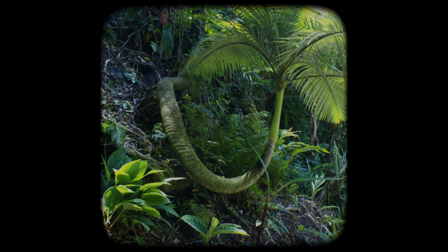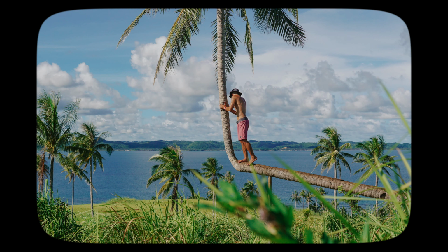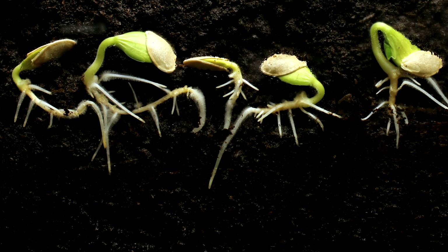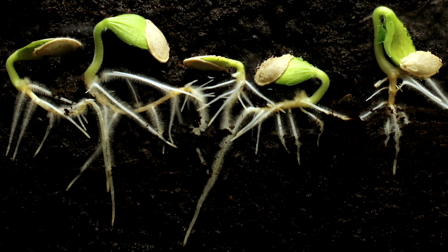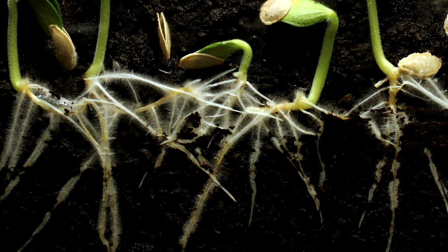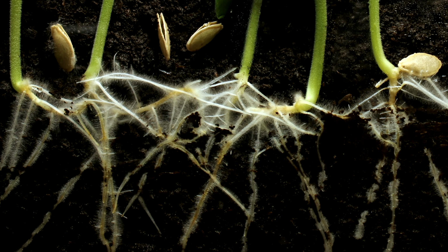When a tree grows on an inclined plane, it tends to straighten itself up through tropisms, that is, by growing towards the sun, and this reduces the total overturning moment that the roots have to resist. It is observed that the root of the tree grows in the direction opposite to the inclination of the tree, and this provides proper anchorage to the tree by facilitating the required resisting moment at the bottom of the tree and thereby preventing the tree from overturning as a result of eccentric growth.